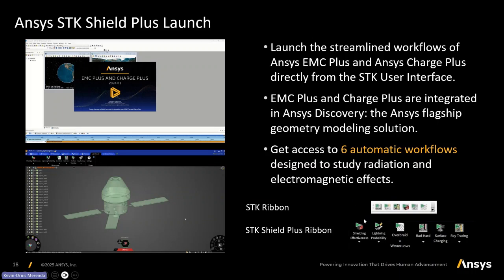So the workflows are shielding effectiveness for electromagnetics, lightning probability for calculating the risk of getting struck by lightning on a given aircraft mission, shielding effects from an overbraid from electromagnetic environments, the rad-hard workflow for being able to understand dose depth curve and model dose depth curves, surface charging for the risk of ESD on the surface between 2 different materials, and then ray tracing to understand dose at the component level on a PCB or inside a satellite.